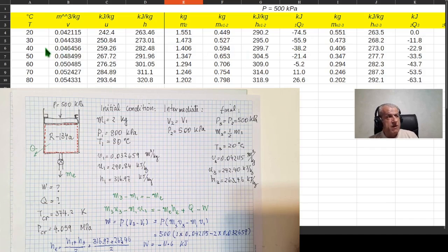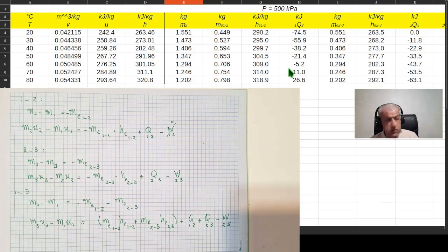So these are different possibilities, depending on how much we open the valve and increase the mass flow rate, or how much more heat transfer we have. Of course, here we have to add heat to the cylinder to keep it at these two points, which is perhaps what we won't want. So if there is no heat transfer for the process 1-2, I would write this here.